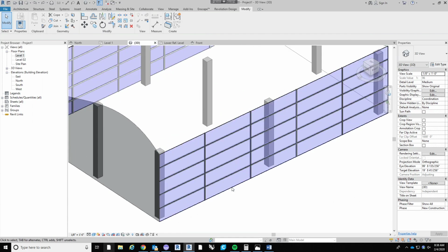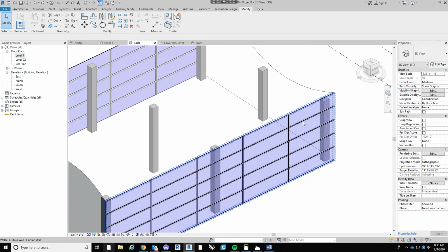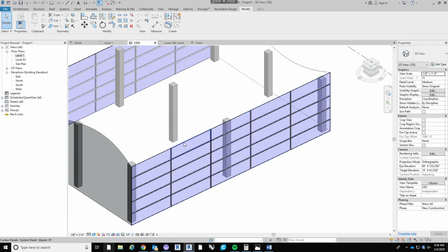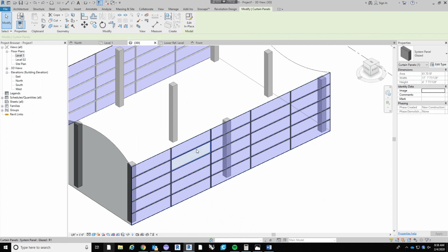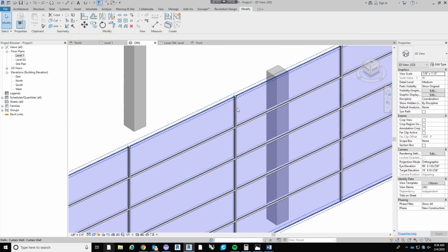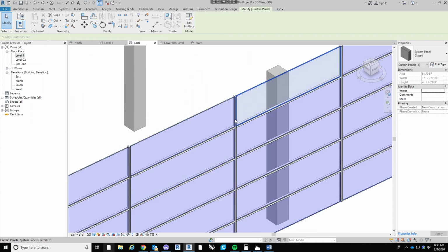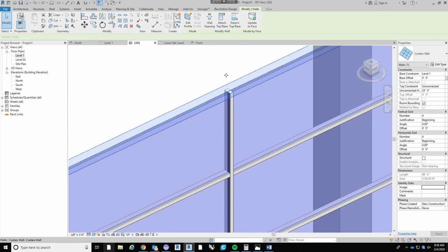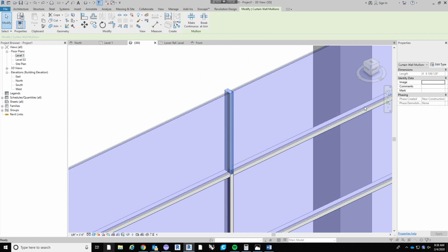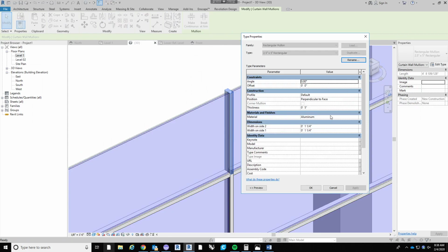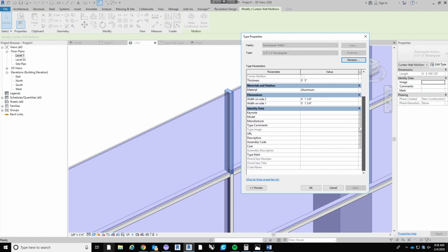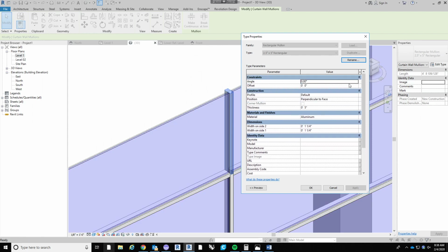So there's two different elements within the curtain wall that you can manipulate. One is the curtain panel, one is the mullion. And the mullion, so you can use, we've gone over this, how to create vertical fins before, and reveals, if I can select the damn thing. And that's fine. You can use the rectilinear mullion to then duplicate and create new rectilinear formed mullions from that, and use the different parameters, the thickness and the width.